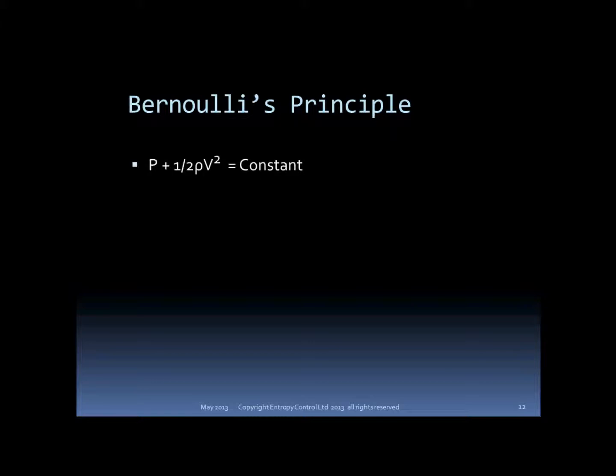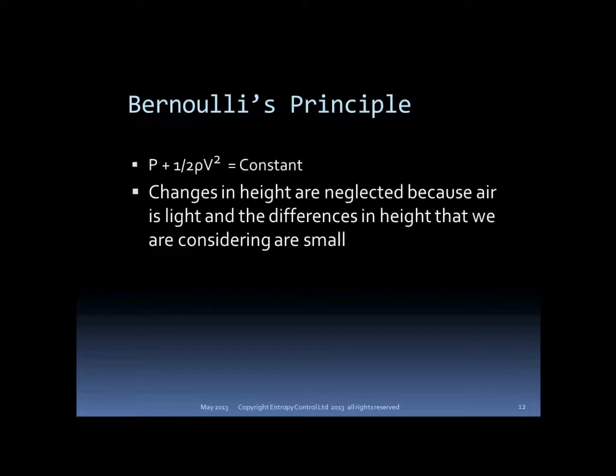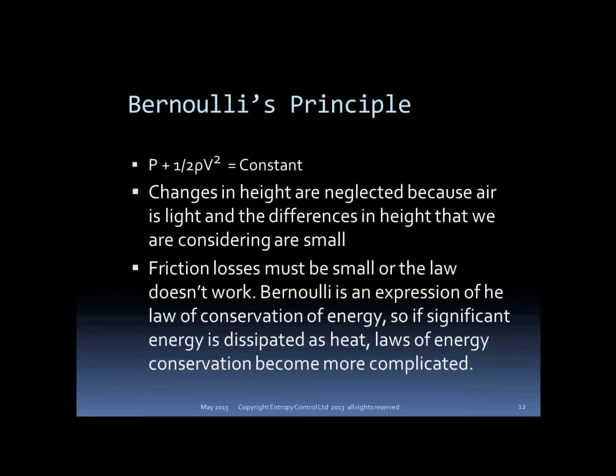Now, Bernoulli, as we use it, is not exact. For instance, there is a height term that we ignore because its effect is very tiny. And then Bernoulli only works where energy is not dissipated as heat. Fortunately, that applies to almost the whole of the flow field, and the places where it doesn't work are well defined.